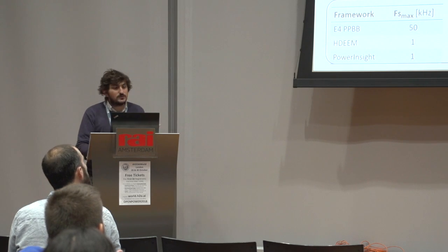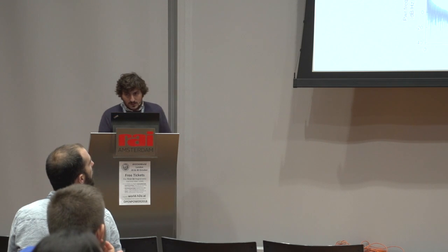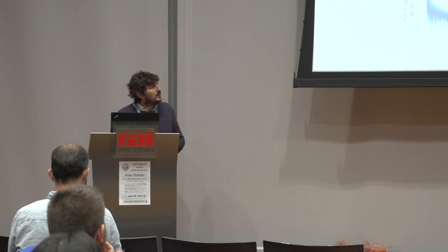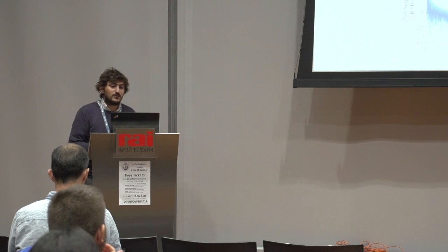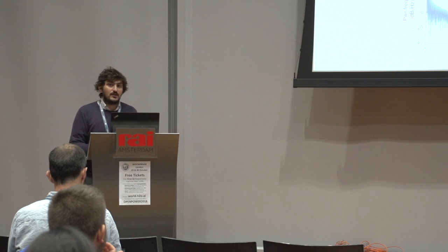Okay, but nice. What do we do with this high-frequency power monitoring? The first insight we can gain from high-frequency power monitoring is that we can now do live spectral analysis of the power consumption, and we can discriminate the different applications which run on the node by looking at their spectral components.